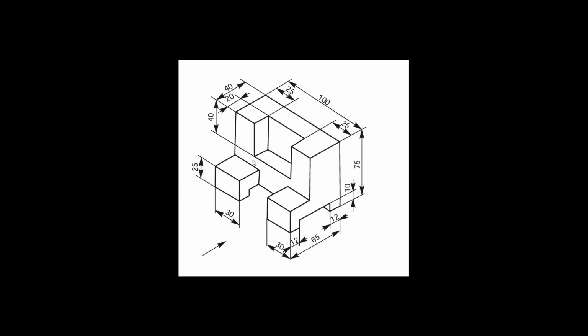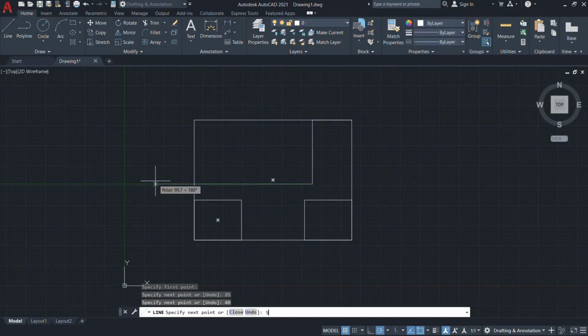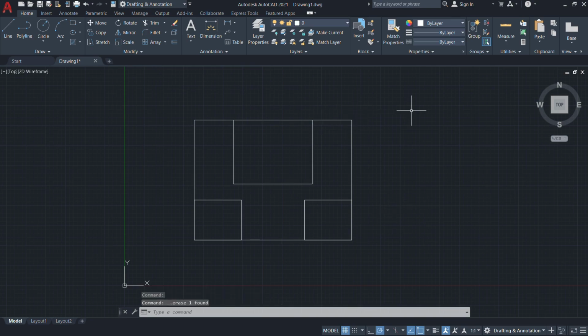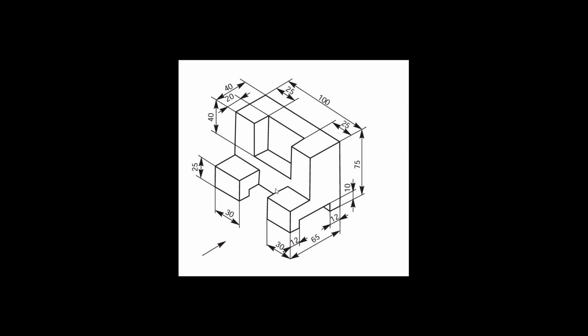The horizontal dimension is also the same kind, 50 mm. 100 minus 25, 25, overall 50 mm. So mention 50 mm horizontally and the vertical dimension is 40 mm. Now the pocket is also determined clearly in the visible areas. Next we need to draw the non-visible portions. That is, look at this side area.